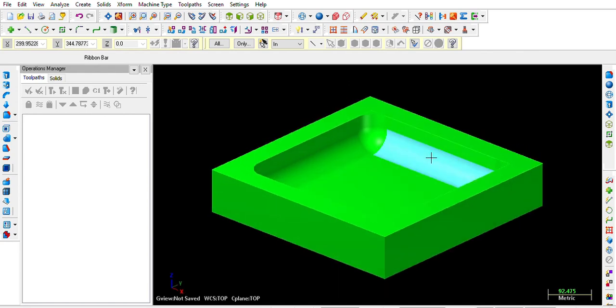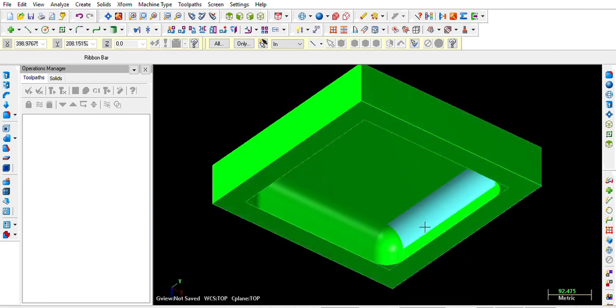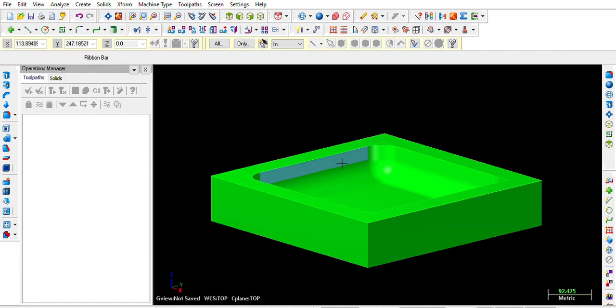Right, now let us copy. This is our main object, the main solid object that has been generated. I would like to make changes to this object, but instead of generating the toolpath directly on the solid, because the processing time for generating the toolpath on the solid object consistently takes a large amount of time, I would like to use only the area of my toolpath. The toolpath would be generated only in this localized surface inside the rectangular box. This particular pocket is where I need to generate the toolpath. So I would consider only the surfaces where my toolpath is required to be generated, and omit the outside surfaces of this solid object.